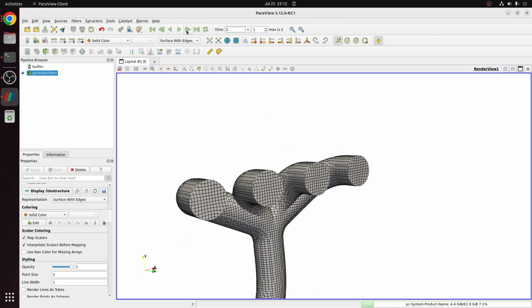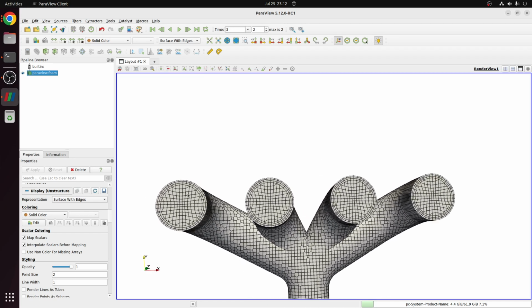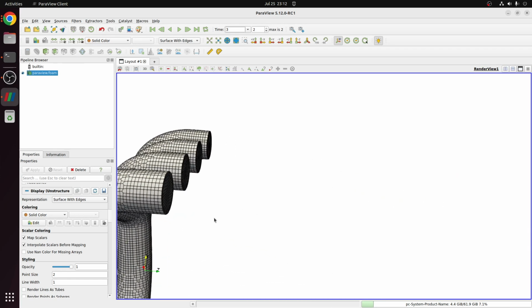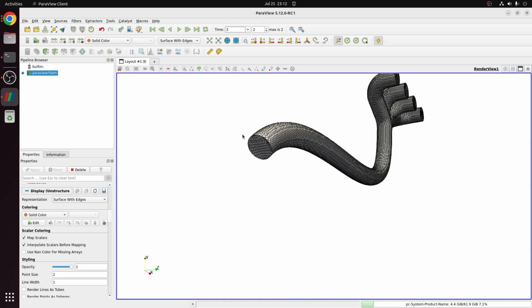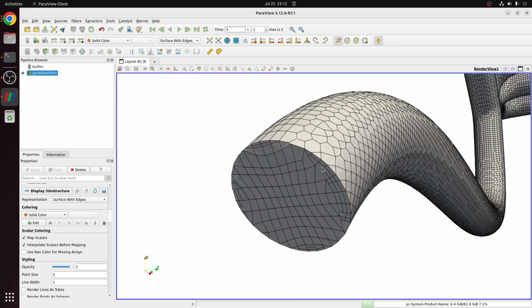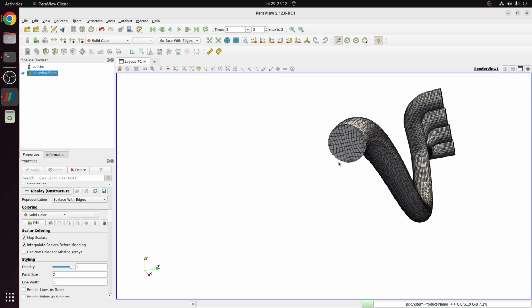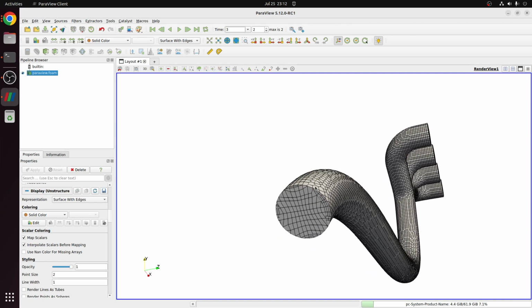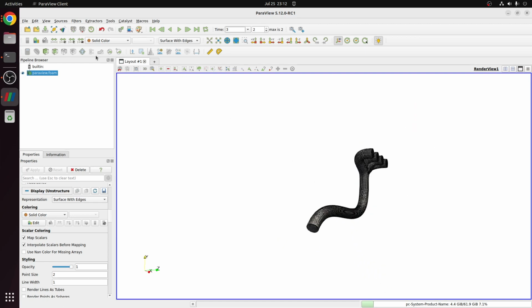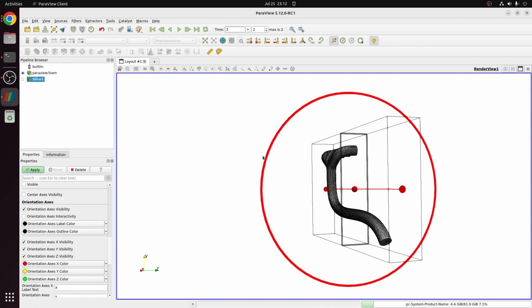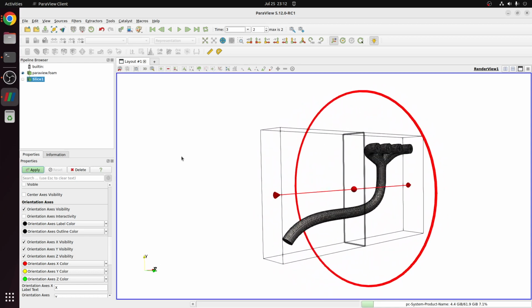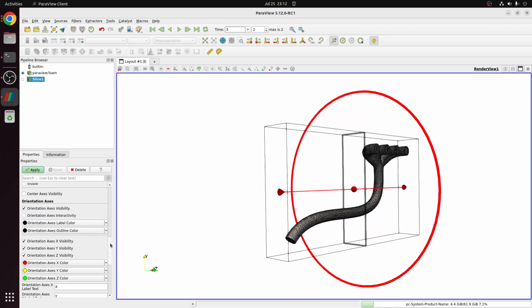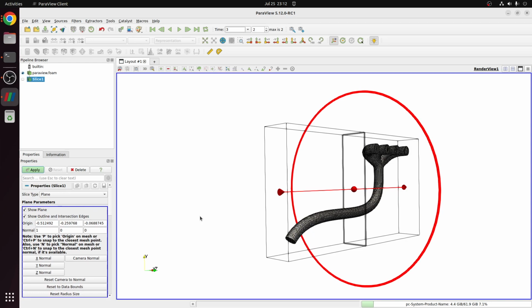Now we have also created the boundary layer. Boundary layer will be in the third. You can see that boundary layer also is generated. Here it has not generated, but we have to see the cut section. And also our mesh is not very good, I would say, because it's still 15 cells across diameter. That is not good. Typically we give at least 20 cells, right?